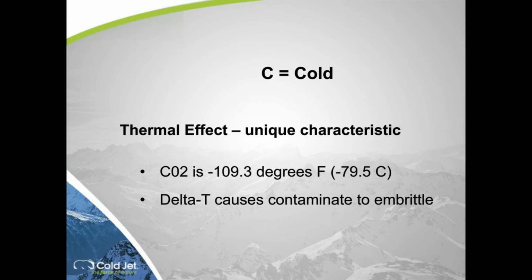But the higher that delta T, the more this effect contributes to the clean. 500 degrees C, it's been estimated and calculated to be 50% of the clean. So translate that. If you clean something that's hot, you don't let it cool down, it will clean easier, it will clean faster. And if you're wondering what's the magic in that, the magic is the thermal effect of the dry ice cleaning is contributing more on a substrate that's hot.